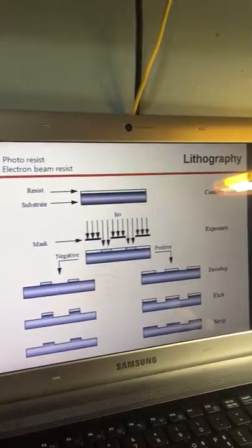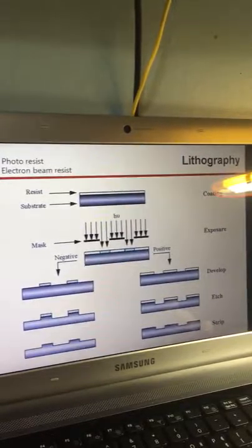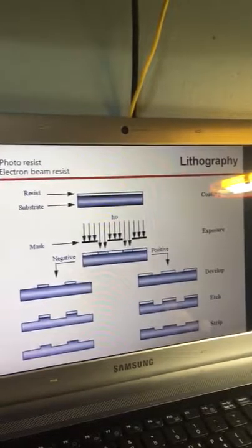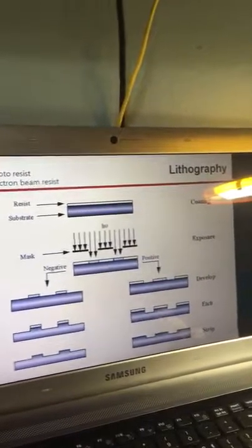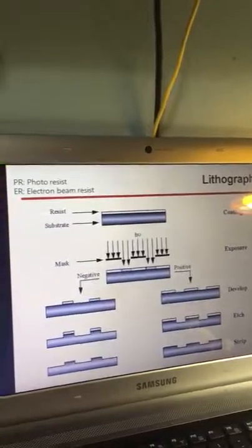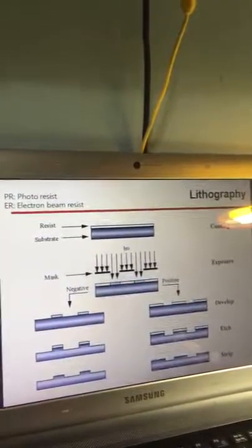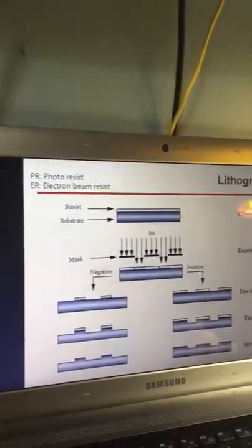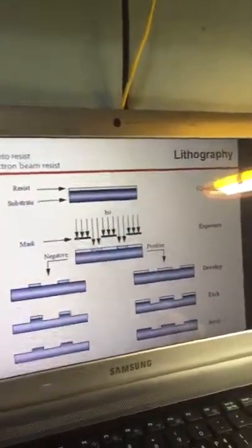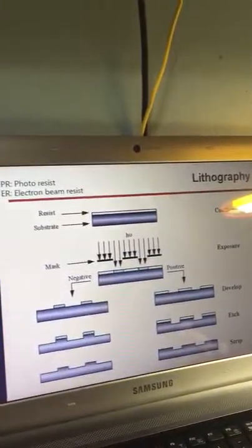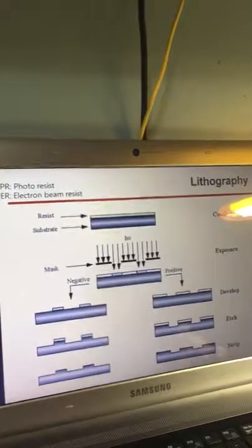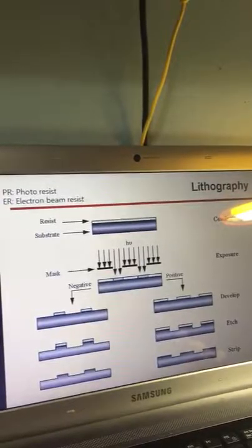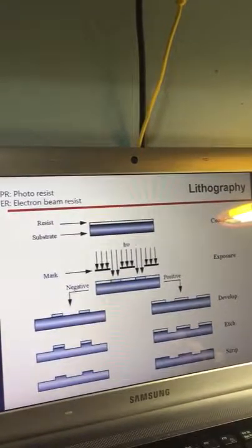First, photoresist material is spin coated on the surface of the wafer. Second, the spin-coated layer is exposed by ultraviolet rays, electrons, and X-rays. At this moment, the tool, mask, and computer data decide which part to expose. Third, depending on the PR layer's resist type, in the process of development, it will remove the exposed or non-exposed area. At this time, the part that you want to remove is removed by melting with a developer.